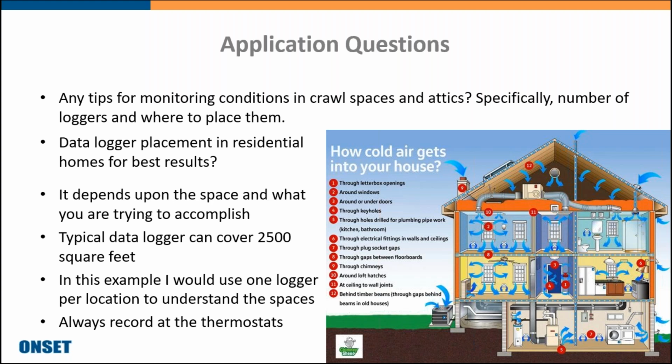But really, it depends on the layout of the space and what you're trying to accomplish. Our data loggers, we say they can typically cover about 2,500 square feet of open space. And in this illustration you're seeing here, I would probably recommend using one data logger per space.